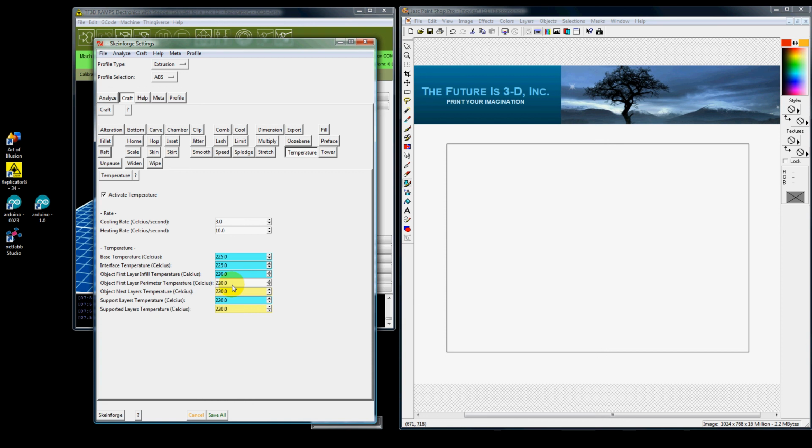So let's say you're doing a wine stem, you want to stay hot, and then you want to start lowering in temperature so you don't have your plastic melting. It depends on the plastic that you use. Every type of plastic has different properties. So your black to your white to your clear. Your clear and your natural melt at the lowest temperatures.